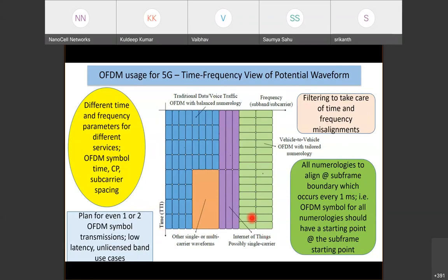You can see that in some cases the OFDM symbol is long, leading to shorter subcarrier spacing. In some cases, the OFDM symbol is relatively shorter. So you can find all cases, and here, for example, the subcarrier spacing is longer. So you could find mixtures addressing different applications.